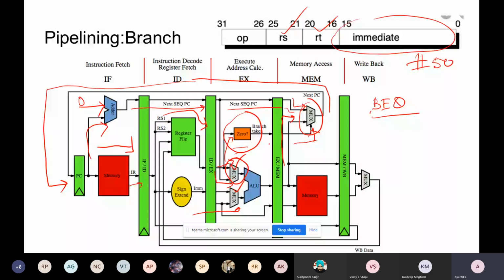So whatever possible usage you are making of your ALU according to your instruction set, because your ALU is one. Whenever you want to do some addition or multiplication, you have to use that same ALU. Maybe the addition requirement is coming directly from your instruction. Maybe it is coming to update your program counter to understand where I will go next. Maybe sometimes that ALU usage request is coming from the types of branching you are handling.